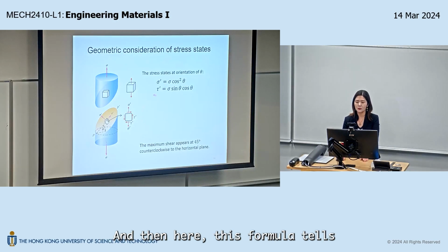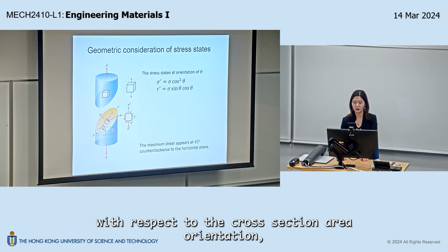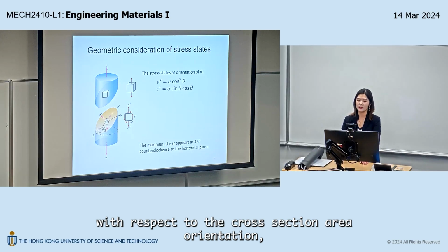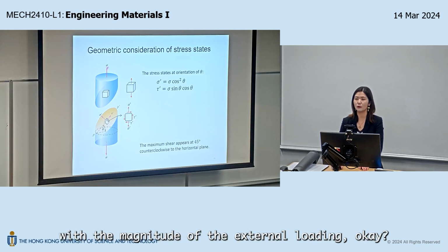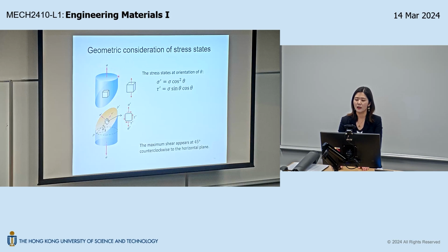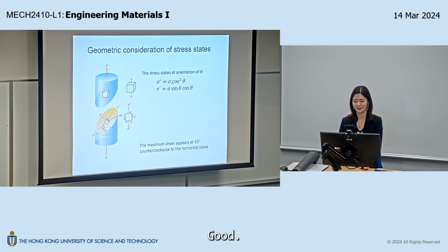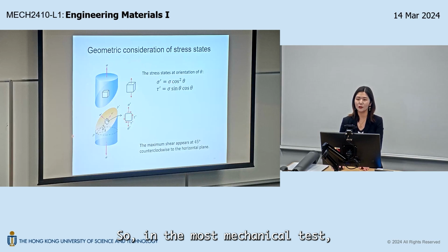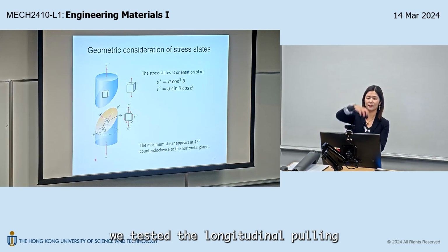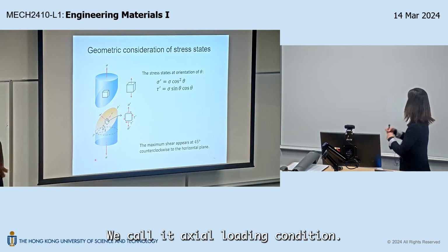And then this formula tells how to calculate the values for a different orientation, at angle theta with respect to the horizontal cross-section orientation, given the magnitude of the external loading, okay? Did you learn this formula already? Good. So you just need to know how to use it, okay? In most mechanical tests, we test longitudinal pulling or longitudinal compression. We call it the axial loading condition.